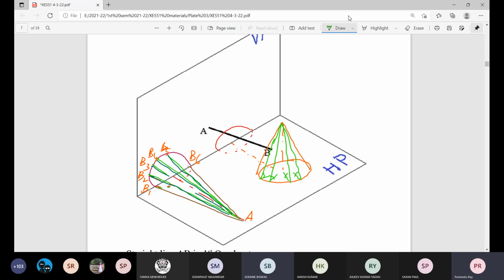Similarly, here also, we are simply considering the other way, that is, it is as if it is not possible to stand on the vertical plane, but geometrically it is equivalent to this, that this axis is perpendicular to the vertical plane, and we are considering half of the cone, as if 50% is below HP, 50% above HP. Then the length of the generator is same, and the angle made by the generator with the vertical plane, that is also same.